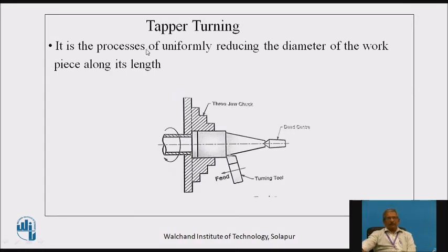So this is the taper turning. Then eccentric turning I already wrote. So prior to that we will study the taper turning. In this we are removing the material along the cylindrical part, but of different depth. Here we will be removing more material, here we will be removing less material. Once we have carried out turning of this diameter, then in this removal, if you observe, we are removing